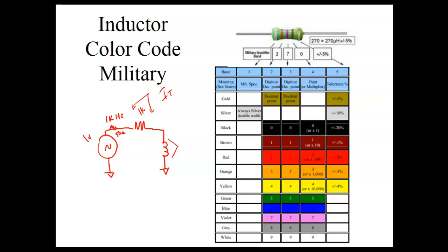Unfortunately, what that means is, y'all probably noticed that when you change things, like if you change the frequency, X of C goes down, which causes the total opposition to go down, and probably the output of your function generator went down, so you have to keep adjusting it up to keep it the same. That's because of that 50 ohm resistor. There's another reason why it's 50 ohm, and I'm not going to get into that. Well, we'll talk about it just a little bit.